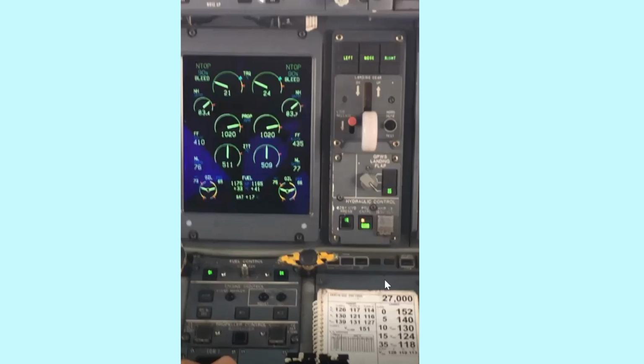If we use Supplement 75, where it says you use autopilot with flaps 35, which has been done in this particular video and this flight which I did, you will note that for the autopilot to keep the pitch and the rate of descent, we have to apply a torque of around this value, 27%, but plus or minus 3.